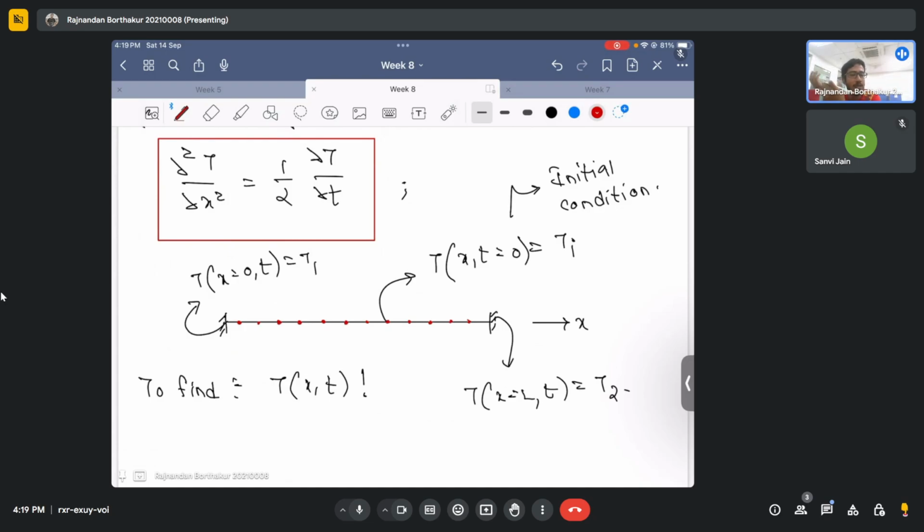But then you can ask why we are not taking grids so close that the distance between them tends to 0. We cannot do that because it comes at an expense. The more grids, the more algebraic equations you need to solve, and that requires more computational power. So it's a trade-off: yes, we need a finer grid, but there is a cost.